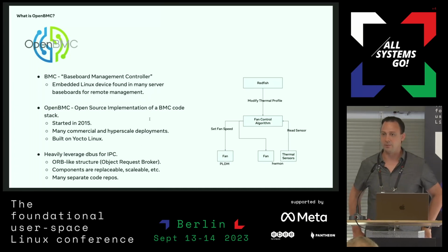Those sensors can be I2C devices, that's pretty common, and then you use the HWMON subsystem. But they could also be, for instance, the NICs or the GPUs have thermal sensors that typically the BMC can get over a protocol called PLDM. You think of SSDs, they've got NVMe MI, so there's a bunch of different protocols that the BMC needs to talk to get something as simple as what temperature are all the devices.